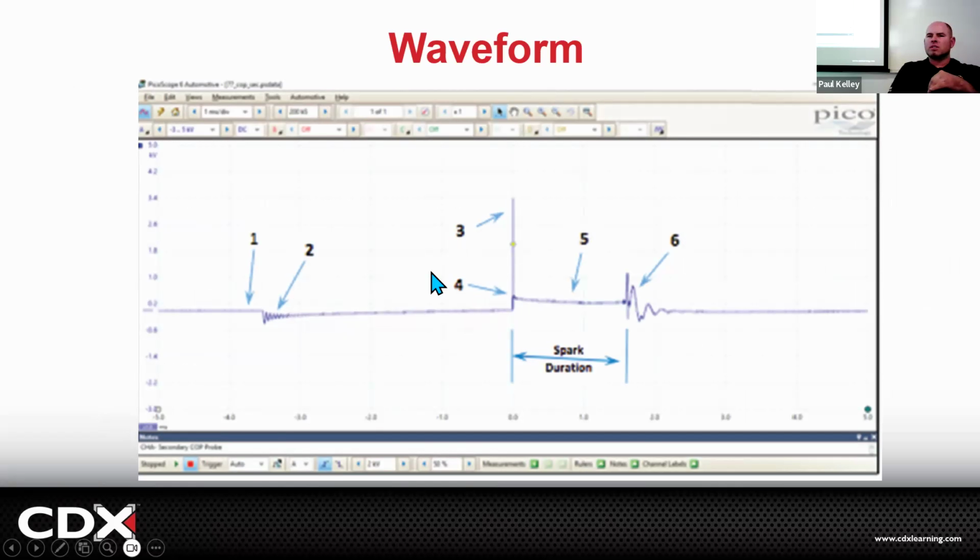But the amount of volts is going to depend on the amount of resistance, right? If you have a lot of resistance, the voltage needs to be higher to overcome it. So give me an example of why there would be a lot of resistance in the secondary. Picture the secondary. The spark plug, yeah, if it's all coated with carbon, there's not a real clean ground.